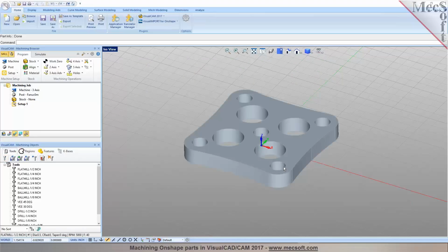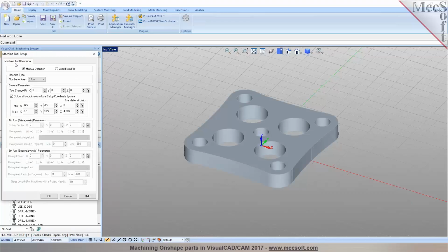Okay. And once you have this information in, you can save them to a library in here. So that's what I got, a library of tools loaded. Now the first step is to define the machining process. For 2 and 3 axis, it's automatically set to 3 axis, which is available right from our standard configuration. You can also program 4 and 5 axis toolpath depending on the type of machine tool you're working with in other configurations.